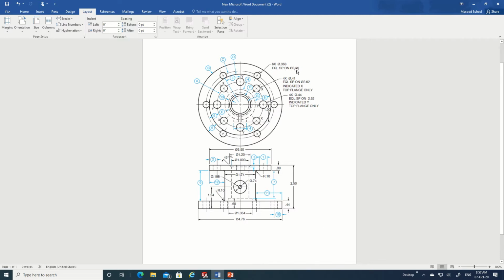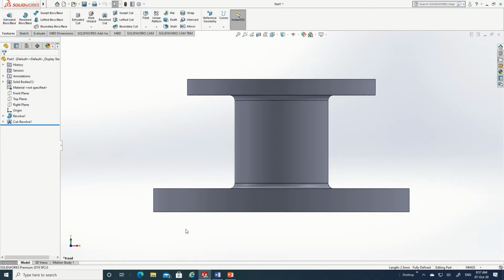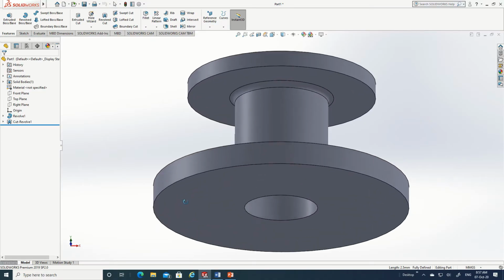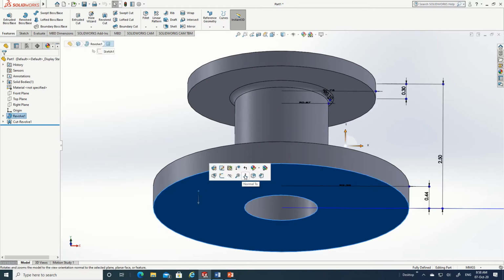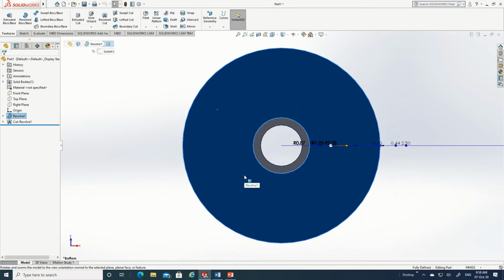Okay, first of all, this is in the bottom flange. So let's go to the bottom flange. Just move the center wheel, press it, turn it. So click on this face. It becomes blue. Select here. It has been selected now. Again, click on that one.